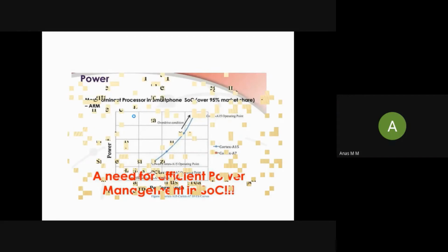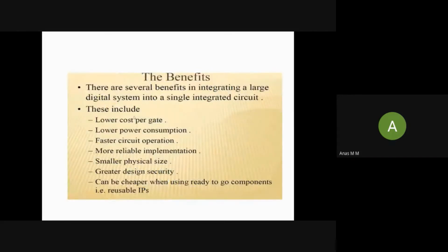So, the benefits of using SoC. There are several benefits in integrating a large digital system into a single integrated unit. This includes low cost per gate, lower power consumption, faster circuit operation, more reliable implementation, smaller physical size, greater design security, and it can be cheaper when using ready-to-go components.